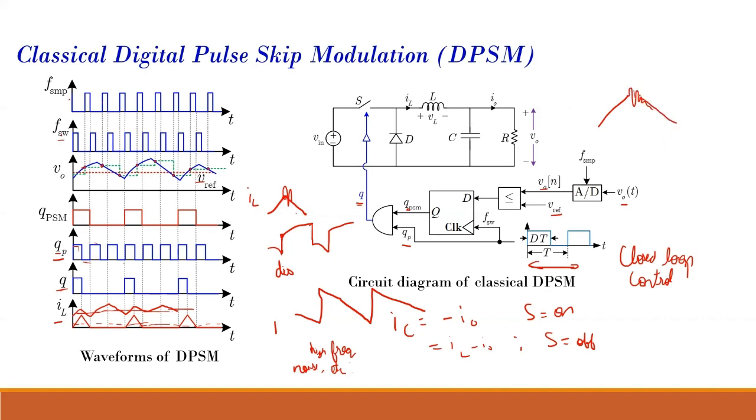If there are oscillations, then you're not sensing correctly. It is not proper. That's why, if you remember, I had mentioned in peak current mode control, there is this blanking period. I don't want the controller to operate in this region because it is undefined, like some random, unpredictable, spurious thing.